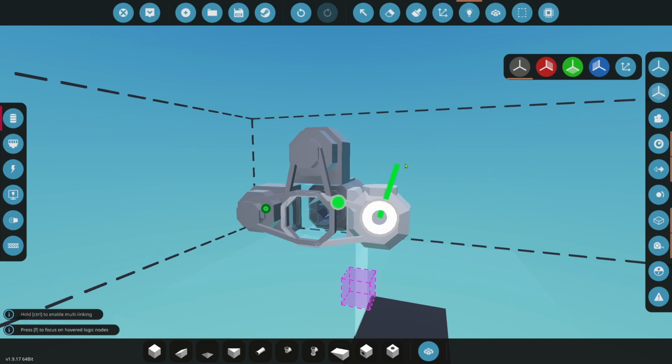Over here we have the same thing, clutch pressure. Now, when we're cooling, for example, it's best to get your engine warmed up, just like in real life. So I tend to like to run my engines a little over 100 degrees. And so often I won't even turn my cooling on until it gets over 100 degrees. So there's a couple ways that you can do this. You could feed it a 1 and it will turn on the pump 100%. And then as soon as it gets below 100 again, it will shut the pump off.